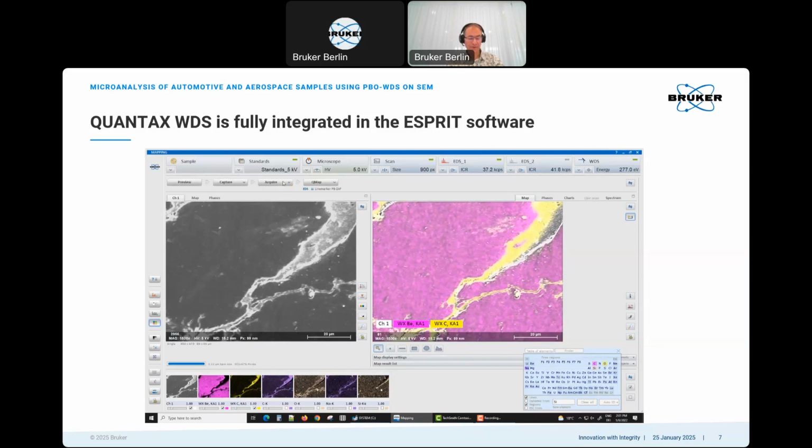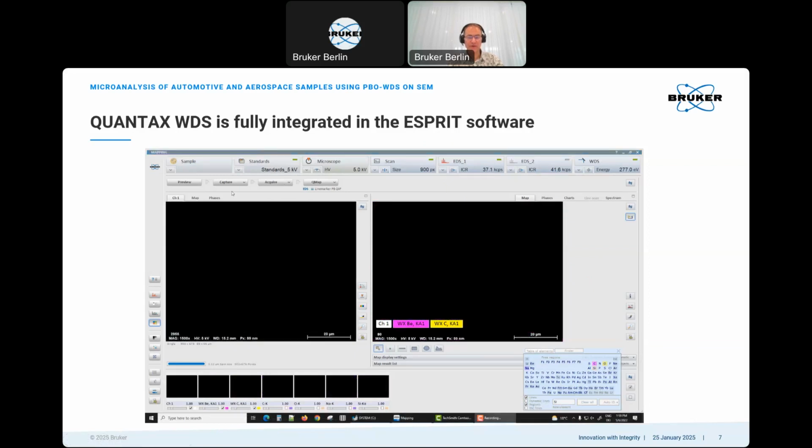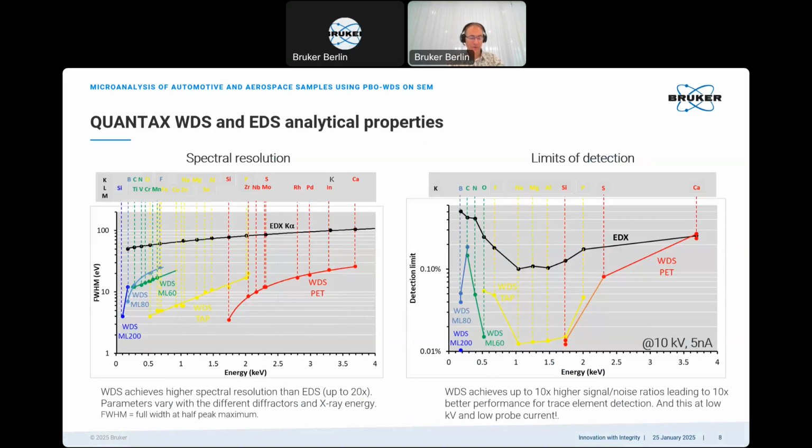Finally, combined WDS and EDS mapping is finished according to the predefined acquisition time of 1 minute for each of the 2 elements. Yeah, so this is how EDS and WDS is combined, and this is to show that the measurement for WDS is energy selective and sequential. Okay, well understood. WDS is energy selective. Measurement will thus take more time.